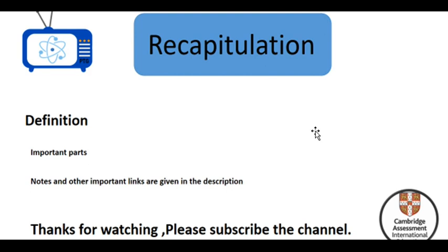What is the function of the split rings? It changes the direction of flow of current when the coil is going to change from left to right or right to left, depending on the rotation direction, which depends on the polarity of the power supply, cell, battery, whatever we provide. But if we change the direction of the poles of the magnet, then the direction of motion will also be changed. If we don't change the poles of the magnet but we change the polarity of the current, again the direction of the rotation will be reversed.